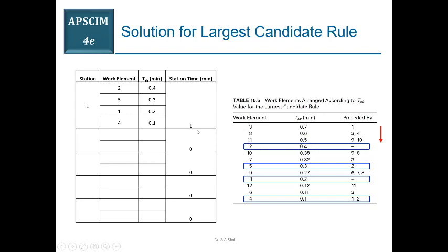particular demand. We can assign more operations to station number 1 also, but it will increase the cycle time of the system. So अगर आप cycle time increase करते हैं, this means that you will be reducing the production rate. The production rate आप reduce करेंगे means that you will not achieve the desired demand rate, जो कि 100,000 unit. So basically you are designing a system to achieve that particular demand rate, which is 100,000 units per year, with a cycle time of 1 minute.